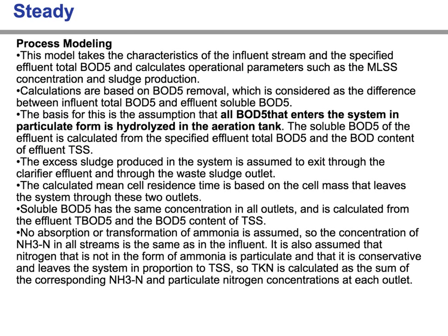Let's explain a little more about the process modeling in steady state. This model takes the characteristics of the influent stream and the specified effluent total BOD5, and then calculates operational parameters such as MLSS concentration and sludge production.